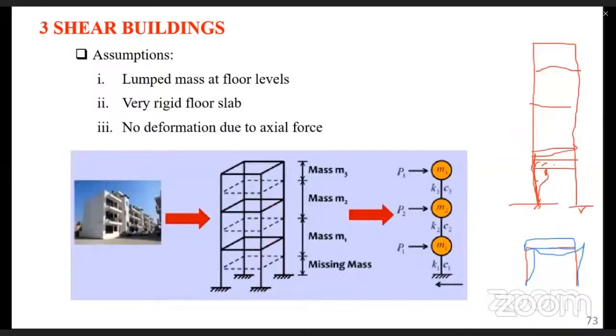Then when you come to design, and you'll find this in the next design course, I think design 4, when you are doing the seismic design and also the wind loading analysis, you're going to look at the cantilever method and all that. You find that you are not considering vertical loads. Why? Because this is a specific analysis that you are conducting to see the behavior of your structure. It doesn't mean that they are not considered in the overall design of our structure.